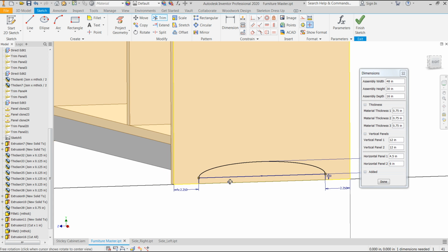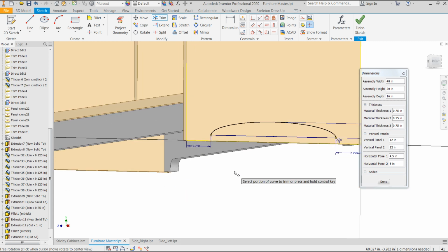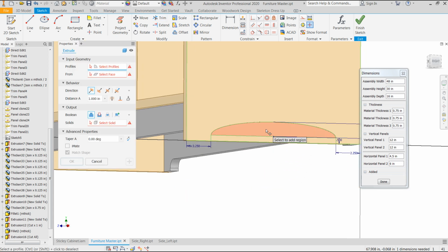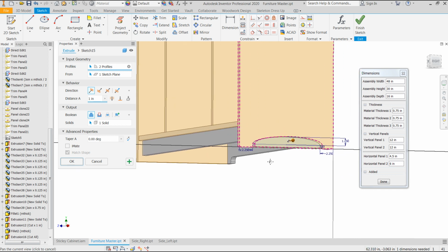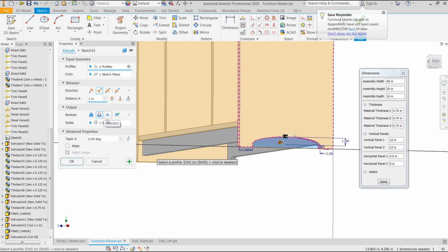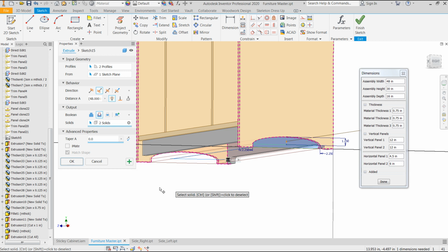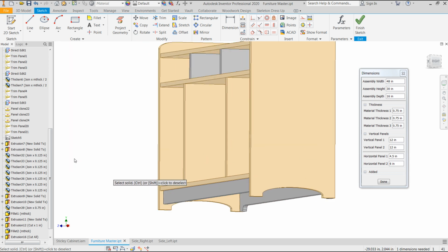If I didn't want to in this particular situation, all I'd have to do is extrude 1 and 2, get them both. Similar to what I did at the top, I want to flip it, cut it the other way, all the way through all, pick solid and touch the second solid that it's cutting through, and pick OK.